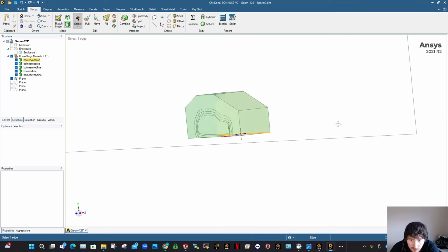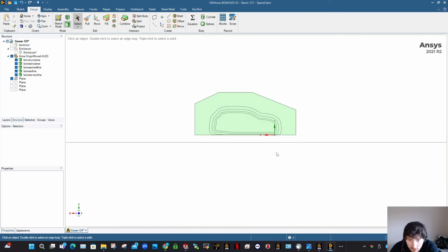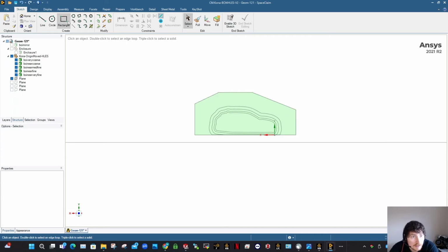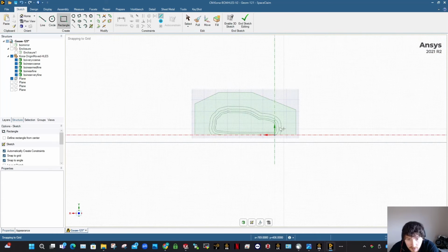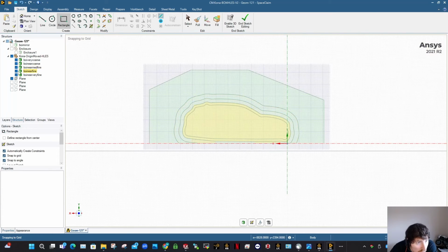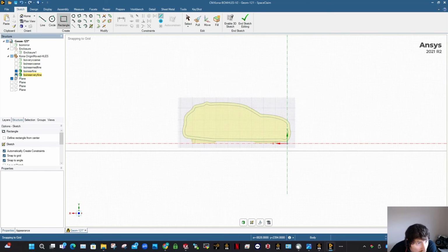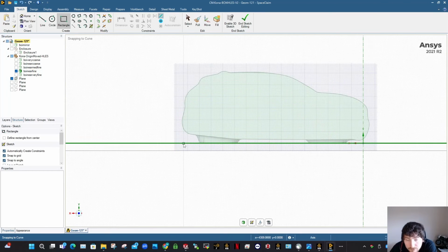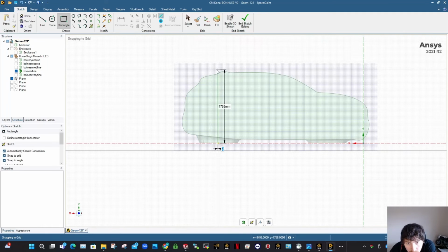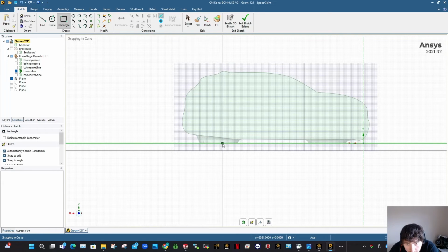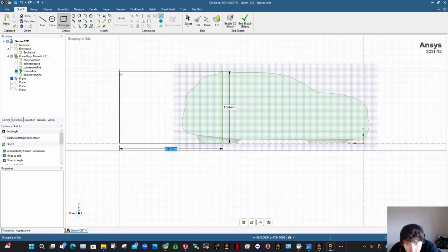So now what I like to do is come in here, look at the vehicle, and do a sketch, get the rectangle. What I do is draw from this region here, the near fine region, and I draw a rectangle that will go from where its wake will be, so anywhere maybe about there isn't bad. I actually grab it through the vortex generators there. So if I go up here and then shoot across maybe about there,